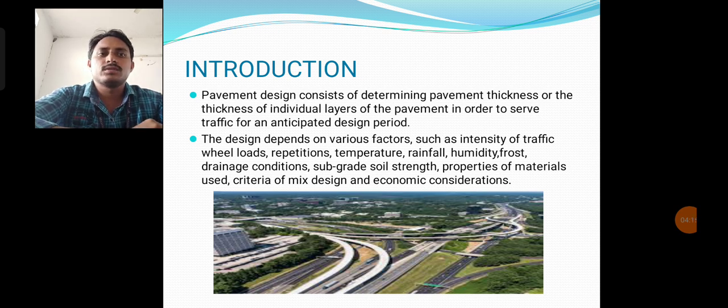We need to provide drainage flow or path so that there is no stoppage of rainwater. Humidity also plays a role in pavement design. Frost, drainage conditions and subgrade soils we already discussed. One of the main factors of pavement design is subgrade soil strength and properties of materials.